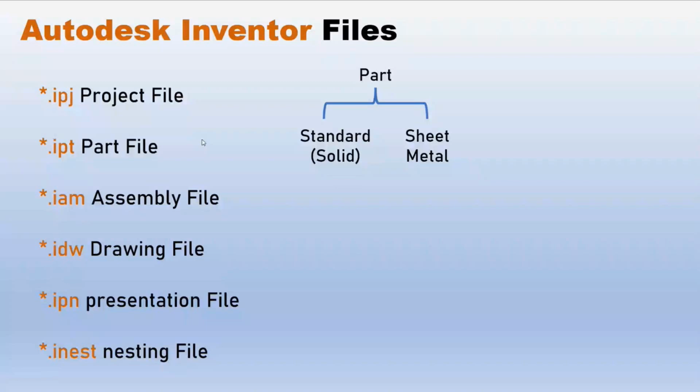So you can use some features like making a flat surface or a rotated surface, or make a loft if you have a loft connection as a reducer, for example. You can use those features to make sheet metal parts. After that, you can use the flat pattern in order to get the blade development.